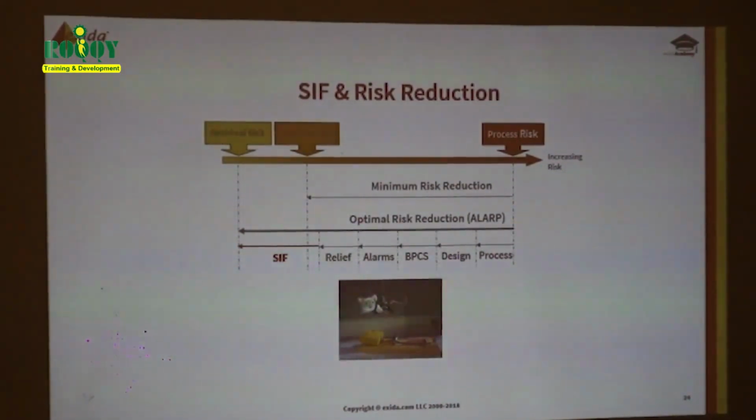Now, through design and through the process itself, you can do risk reduction. You can reduce your risk. So you put it in a tank with a floating roof and maybe a vented space with nitrogen in it to stop the vapor space explosion. So by design and process, you reduce your risk. You then have a process control system that will limit the level through normal operation. You try and stop the overflow when it reaches the top level. Something happens, the inlet valve closes, and maybe you divert the flow to another tank. So you do risk reduction.